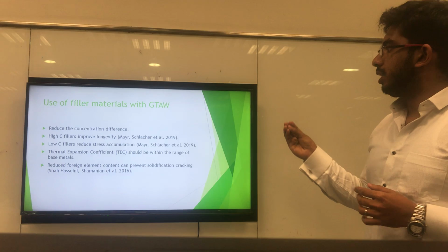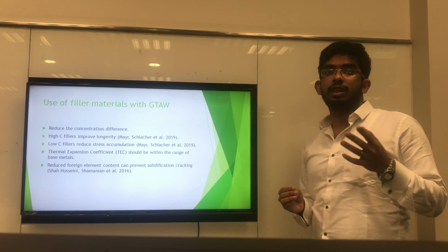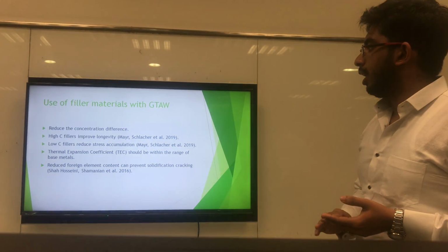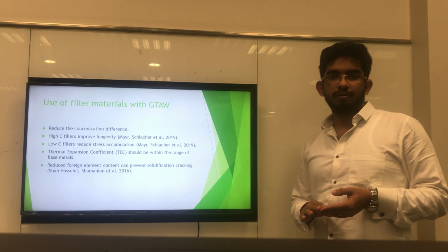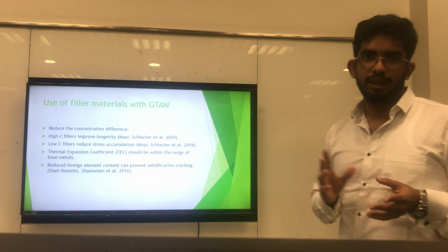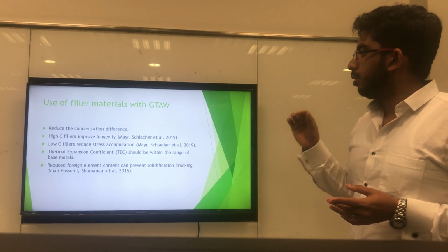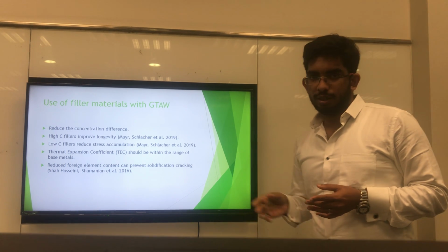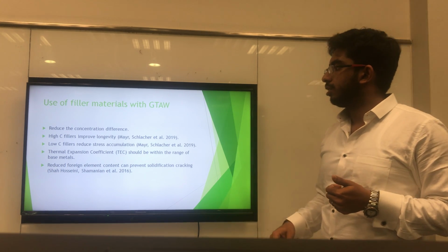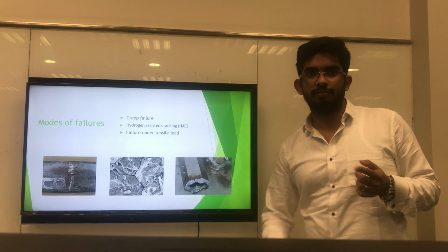Use of suitable filler materials can reduce this concentration difference. A high carbon filler material can improve the longevity, whereas a low carbon filler can reduce the stress accumulation. The thermal expansion coefficient of such a filler should be between these two base materials. It is also recommended to reduce the content of impurities. In certain cases, nickel can be used to reduce carbon migration, which is one of the plus points of nickel.